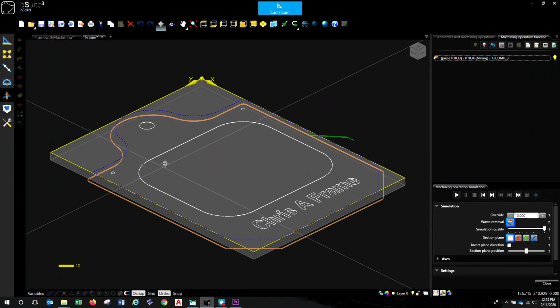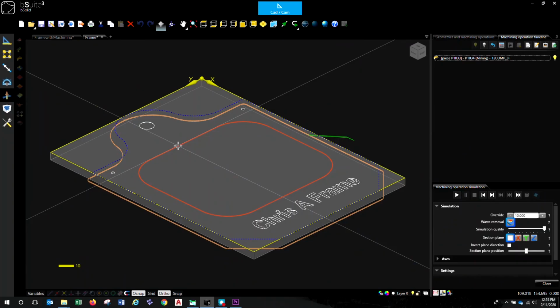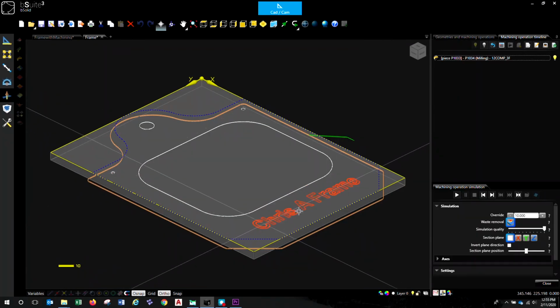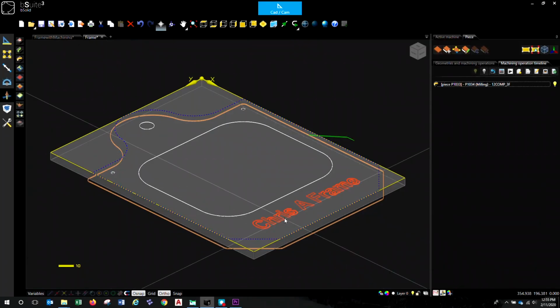So we're going to use standard milling for this section of geometry here, except we'll go internal rather than external for our tool correction. And then for this text down here, we'll try and use the 3-axis 3D engraving, which does a lovely finish on text. And we'll pocket this hole out as we don't have a drill that's 20 mil in diameter.